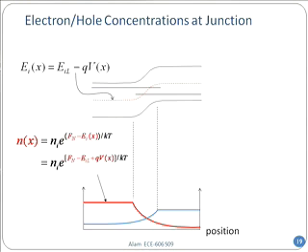But first, let me convince you that the carrier concentration will be given by this red line. Do you agree? n equals ni exponential of Fn minus Ei. That you agree, right? That's the traditional expression. Now Fn at low current is flat up to the other side of the junction, so I shouldn't really have to touch Fn. So I keep it the same.